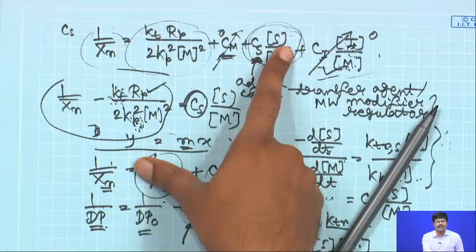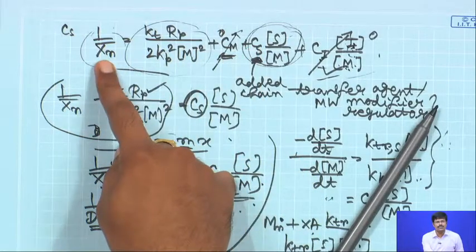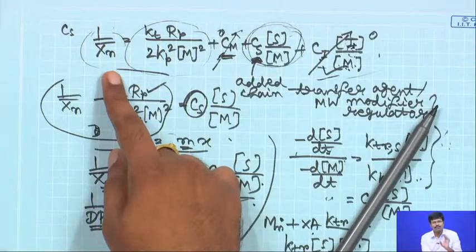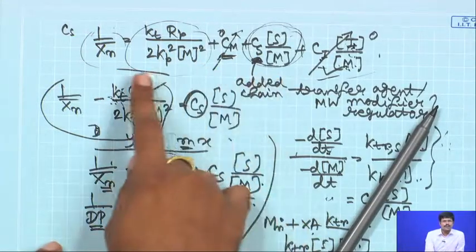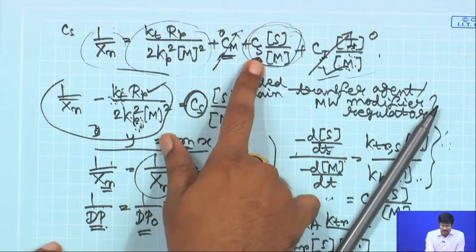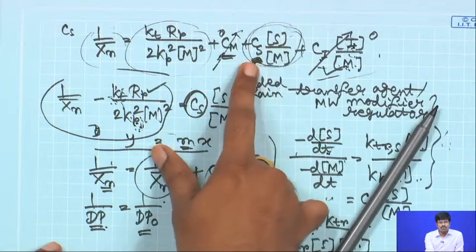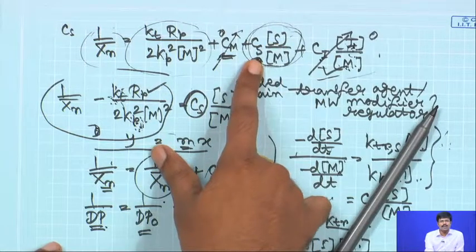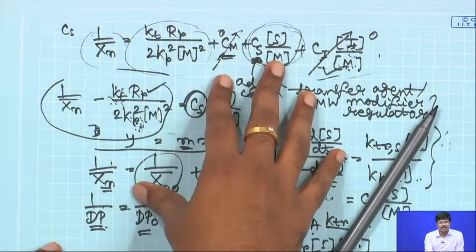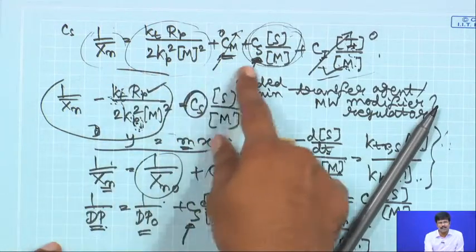or you do not want to go to a particular concentration where there is a lot of chain transfer and your Xn bar becomes too low, because even if you want to make it lower, you want it to be in a particular range. So, measuring the value of Cs becomes important. You have to adjust the concentration of the chain transfer agent and choose the particular chain transfer agent, because for that chain transfer agent and monomer pair this Cs is valid, because for a particular monomer you have a specific kind of propagating species.